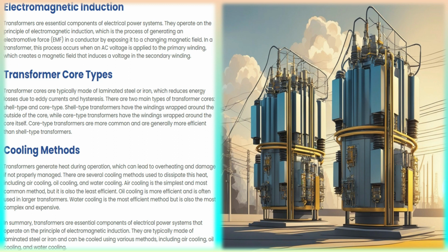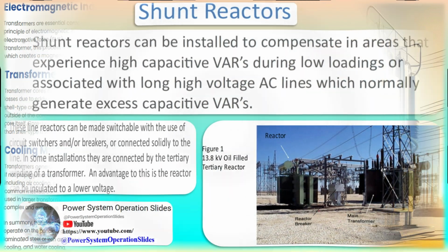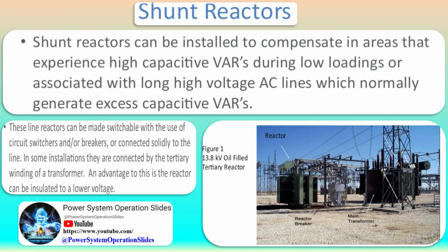A transformer is a passive electrical device that transfers electrical energy from one electrical circuit to another, or multiple circuits. A varying current in any coil of the transformer produces a varying magnetic flux in the transformer's core, which induces a varying electromotive force across any other coils wound around the same core. Electrical energy can be transferred between separate coils without a metallic conductive connection between the two circuits. Transformers are used to increase or decrease the alternating voltages in electric power applications.